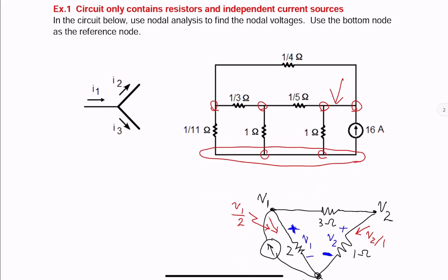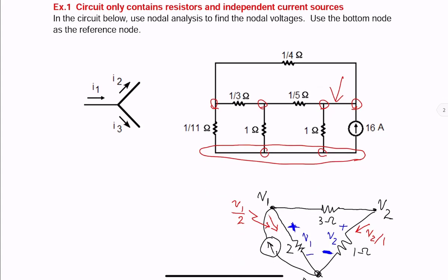For Kirchhoff's current law, the easiest version to get a feeling for is the summation of currents coming to a node is equal to the algebraic summation of currents leaving the node. In other words, for the little figure that we see here, I1 equals I2 plus I3. I1 gets to the node, splits into I2 and I3.